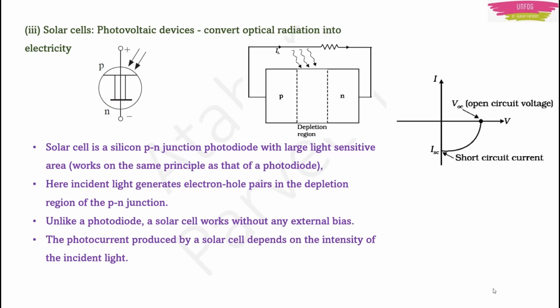Okay. Now what will be the working of this solar cell? Here we don't know whether it will be forward bias or reverse bias because we are not connecting any battery in the circuit. But you see the direction of the current. The current outside the junction will go from P to N, isn't it? But what will happen inside the PN junction diode? We know that electrons move from N to P first, right? When electrons are moving from N to P, the current is moving from N to P inside the junction. But outside, current is moving from P to N.